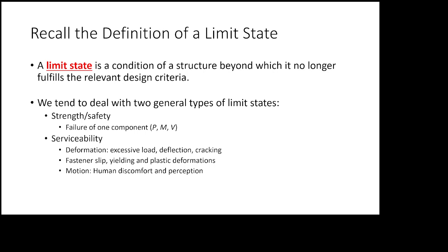As an example, I can tether this to a concept that you had if you took reinforced concrete design with Dr. Zatar last semester. When you dealt with moment capacity and shear capacity, you had to factor the loads, but you did not have to do so when you were looking at deflections and cracked moment of inertia. You didn't use factored loads then. It's because those aren't strength considerations. If the beam deflects too much, it doesn't mean it's going to fall down and kill somebody. It just means it's not performing its day-to-day intended functions. Does that make sense?